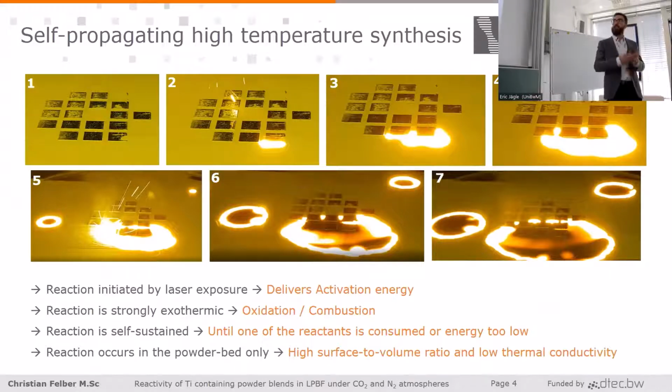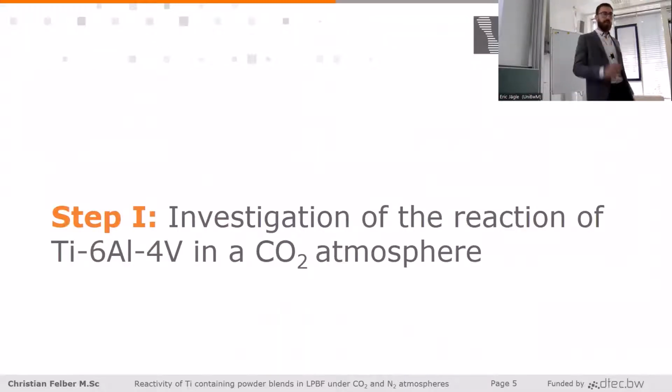We see that the reaction is initiated by laser exposure. It's very strongly exothermic and self-sustained, which means that even after the laser was turned off, this reaction went on until all of the powder was consumed. And it's really important to know that this reaction occurs in the powder bed only, because powder has a very high surface-to-volume ratio, which lowers the activation energy of this reaction, and furthermore, it has a very low thermal conductivity.